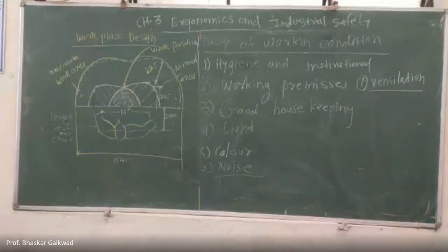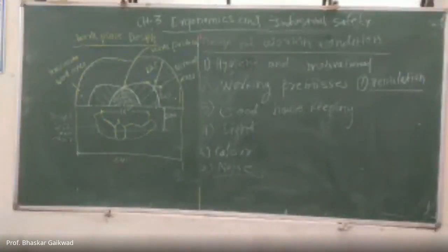So noise. Noise protective equipment you always have to use in the forging industry, mechanical industry. If you are not using it, that worker will feel irritated, and sometimes deafness will be caused, and fatigue will be created in the mind. As far as possible you should avoid noise; around 85 decibels of sound is allowed in the working conditions. And the last is that good ventilation should be there.